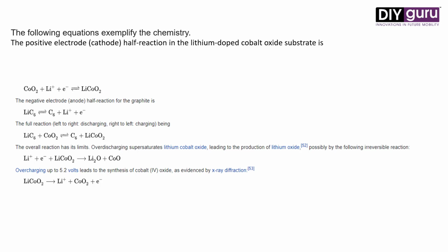After the reaction has taken place and the lithium ion has moved to the anode, in this condition the battery gets fully discharged. Now, when we apply an external source for charging the battery, the lithium ions again move to the cathode, and the electron moves through the external circuit, the electricity which is applied through the external circuit.